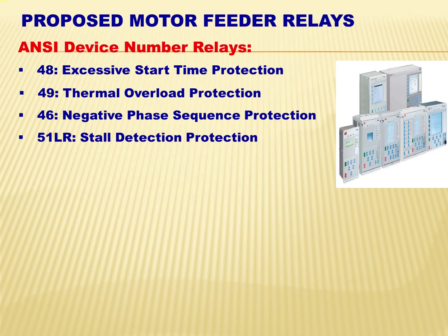The cause of the negative phase sequence currents could be an internal or an external malfunction. An internal malfunction may be a minor or major phase-to-phase fault in the stator windings. An external malfunction could be a depression in one of the incoming phase to neutral or phase-to-phase voltages.